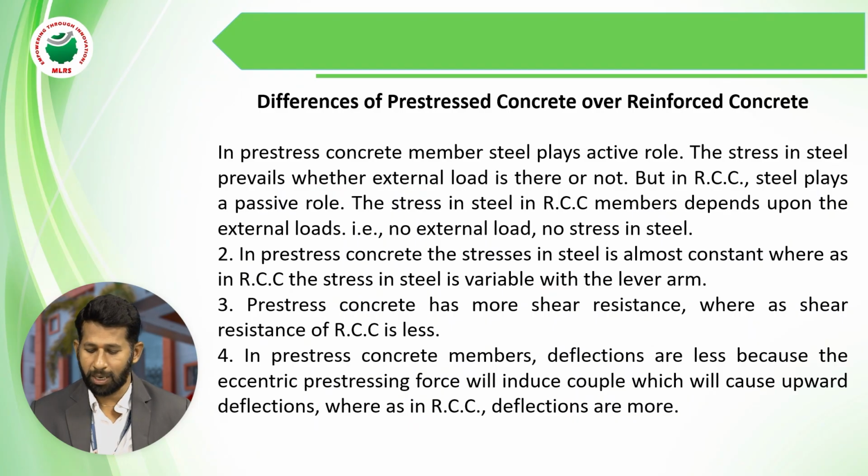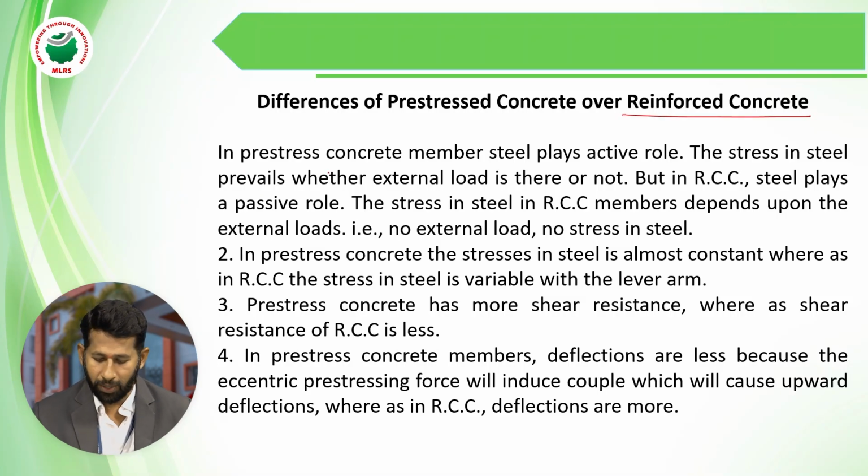Difference between prestressed concrete and reinforced concrete. The main key role of the steel in a prestressed concrete member is that the stress in steel prevails whether the external loads are there or not, but in RCC steel plays a passive role.